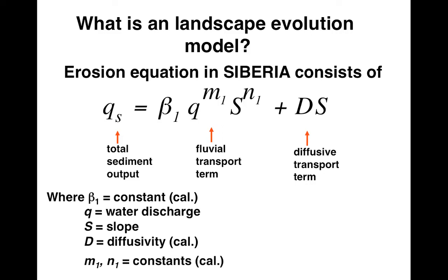So you would essentially simulate the water flow in that landscape and then get the fluvial discharge, which you can use for the fluvial component of your sediment transport. And then the other one is a rain splash component or a soil creep component or some sort of diffusive sediment transport, which is maybe impacted by wind, erosion and other things which tend to smooth out the landscape.